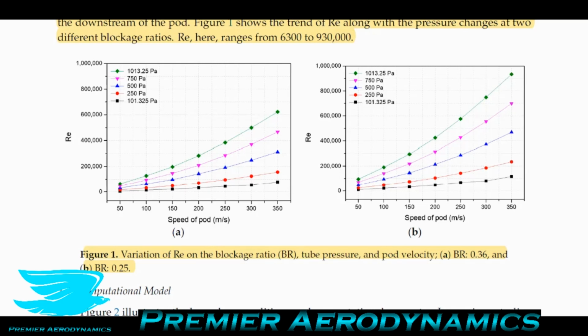So why is that? Because the density is so low. Even though the velocity is really high, the characteristic length is decent. It's not very small. It's not like a little acorn or something. It's actually like a big train. The density is so low that the Reynolds number is very low. So that means you could still be operating in a transitional regime or even a laminar regime, because the Reynolds number is so low and there may not be many disturbances. So that means you can potentially reduce the skin friction drag, because the velocity of the flow near the surface is going to be very low compared to if you had a turbulent boundary layer. So that was quite interesting.